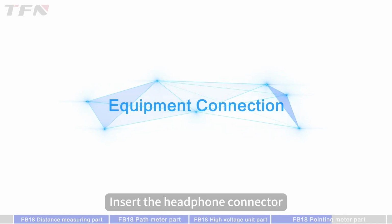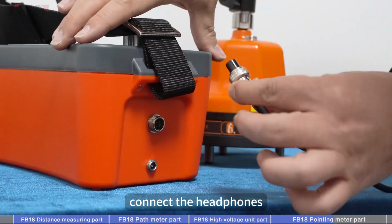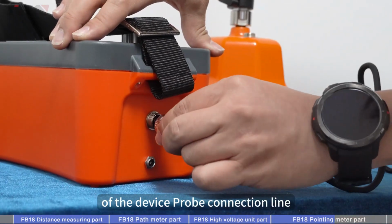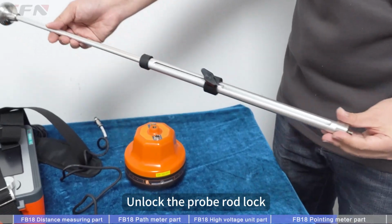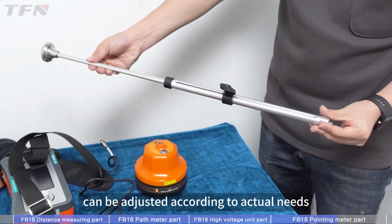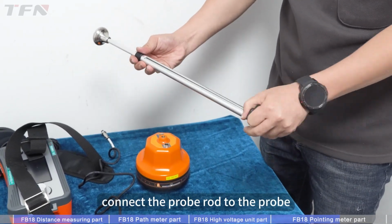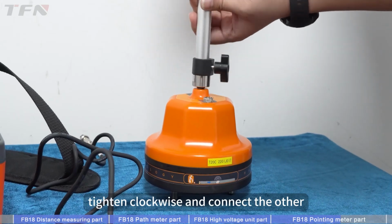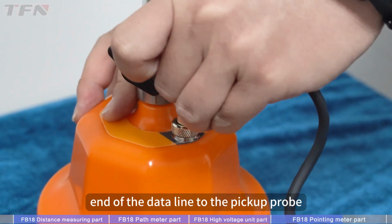Device connection. Insert the headphone connector on the left side of the device. Connect the headphones and insert the right side of the device. Probe connection line. Unlock the probe and rod lock. The telescopic probe rod can be adjusted according to actual needs. After locking, connect the probe rod to the probe. Tighten clockwise and connect the other end of the data line to the pickup probe.